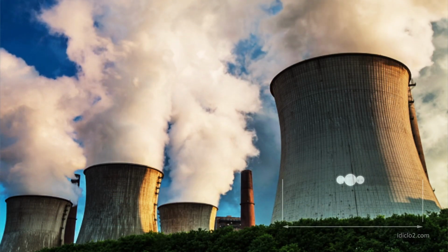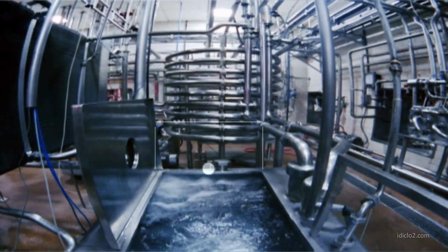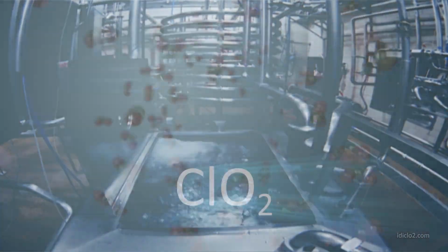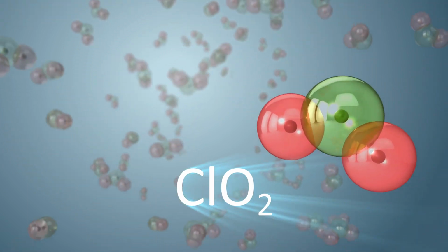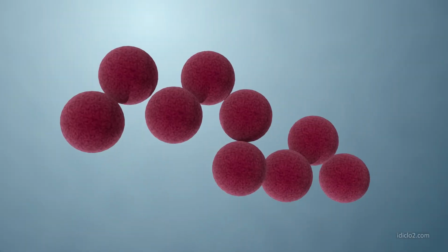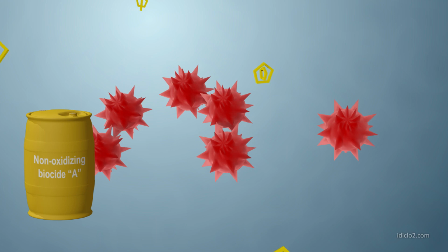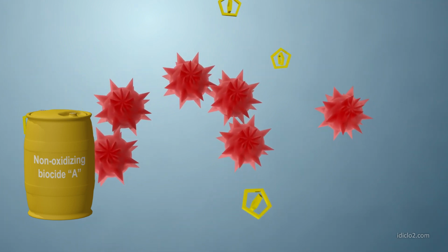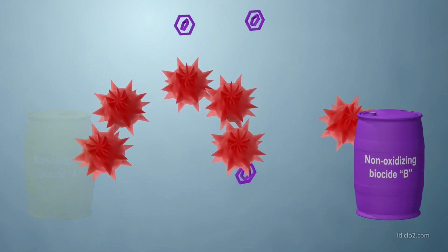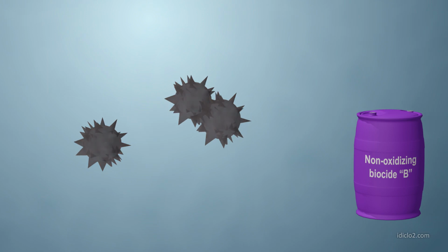ClO2 is a well-recognized biocide treatment for cooling water and process water applications, especially when biofilm removal and inhibition is the goal. Chlorine dioxide is a fast-acting, highly effective oxidizing biocide. Microorganisms are known to alter their structure to develop immunity to non-oxidizing microbicides. The typical solution to this problem is to alternate non-oxidizing biocidal chemistries.